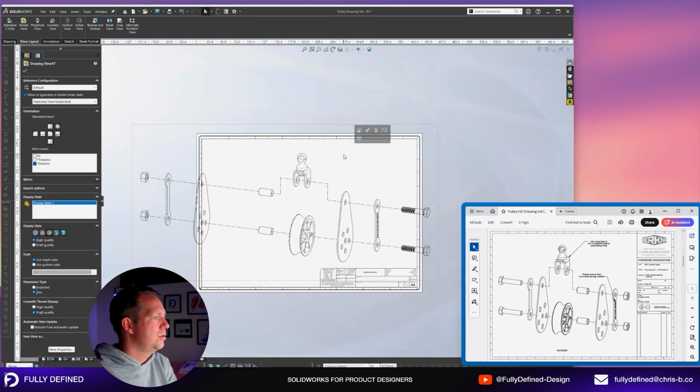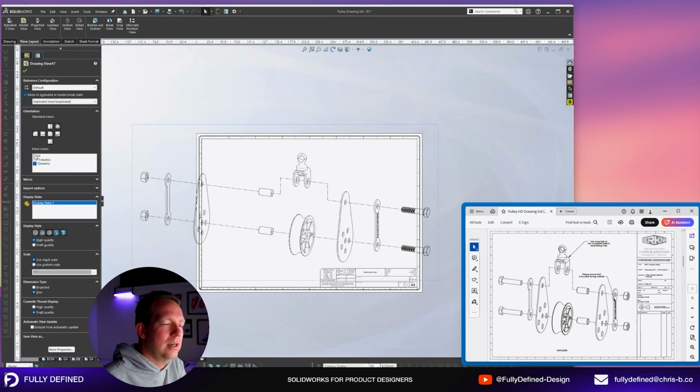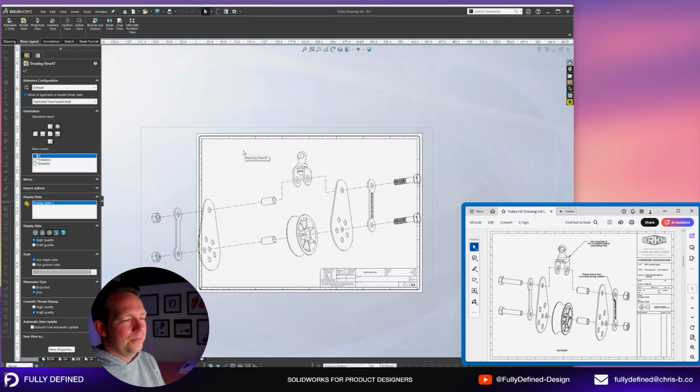And then I can click on this drawing view and you can see under more views now I have this EX that I can click on. And when I click that, the view goes to that drawing angle. So this can be useful for when you're trying to work out with exploded views how far apart your parts or sub-assemblies need to be spaced so that nothing's overlapping. All right? And that's the other challenge in this little task here. You can see in the example page, nothing is overlapping. So we want to do the same thing.